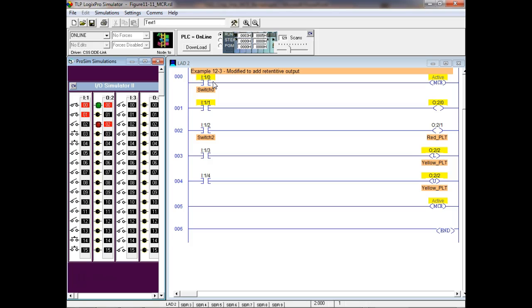So I've got a brake on a motor. Of course, it's stupid to put a brake on a motor that has to be powered to turn the brake on. Most of the time, the best way to do brakes, we got our robots over there from Amtech, which they made 2 of our robot sales. They hooked the directional control valve so if you kill power to the robot, the dang thing's open.